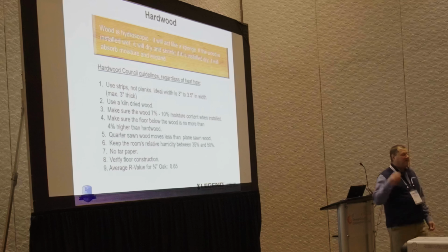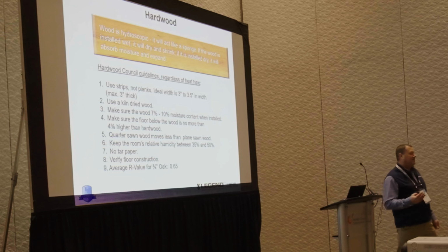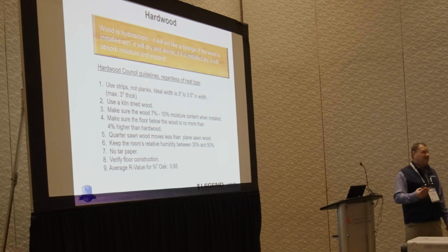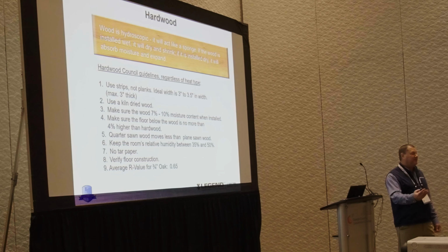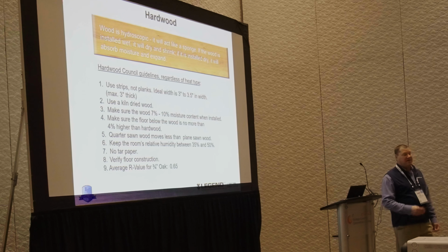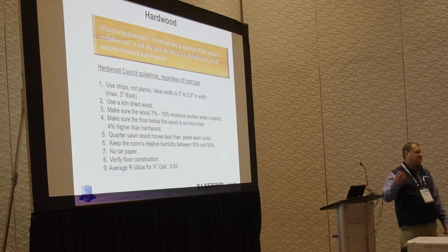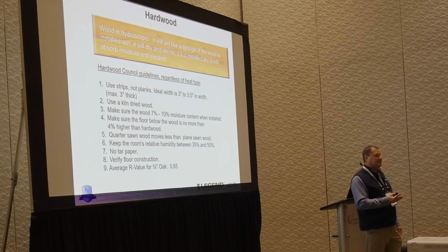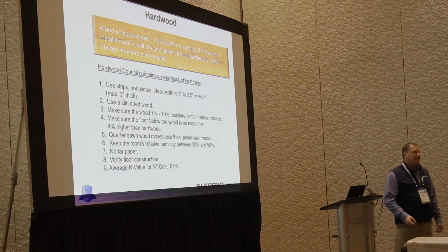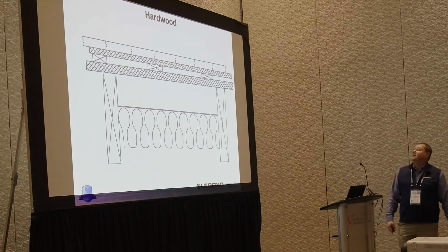So, hardwood floors, definitely you want to look at the manufacturer's recommendation for that. Tell your designer, we plug that information in and we can tell the system don't go over 80 degrees surface temperature. And it will calculate it out. It will tell us if we've got enough BTUs with that lower surface temperature, and if we can't, it'll tell us we need supplemental heat. And we can easily think about that ahead of time rather than after the floor is installed and we've got issues with it. So hardwood's a big deal.